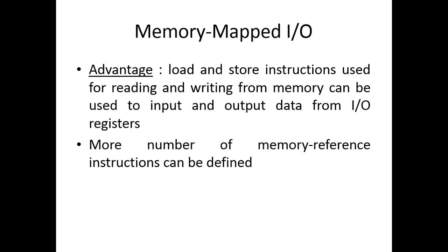No need to spare opcode combinations for defining I/O instructions. Those combinations can be used to define more memory reference instructions. So that is one of the major advantages of using memory mapped I/O over isolated I/O.